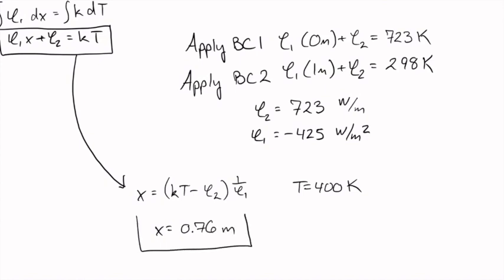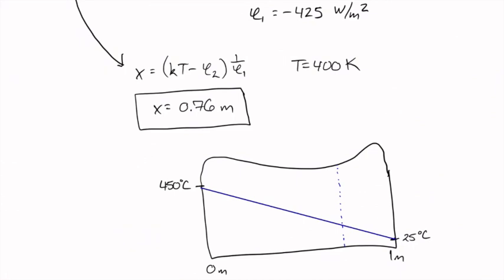And so this is the position of the steam pipe for the case where thermal conductivity is independent of temperature. To really visualize this profile, we need to expand our schematic for the cement wall to include a much more resolved length scale. So doing this for the most recent case where K is not a function of temperature, we get this linear profile as expected, and about a quarter of the way from the cool edge, that's the point where our temperature equals 127 degrees C.